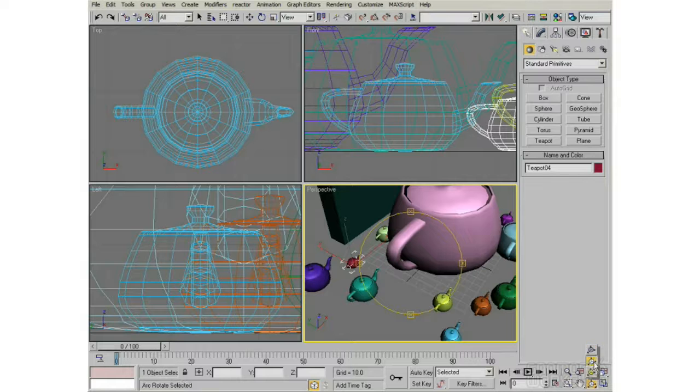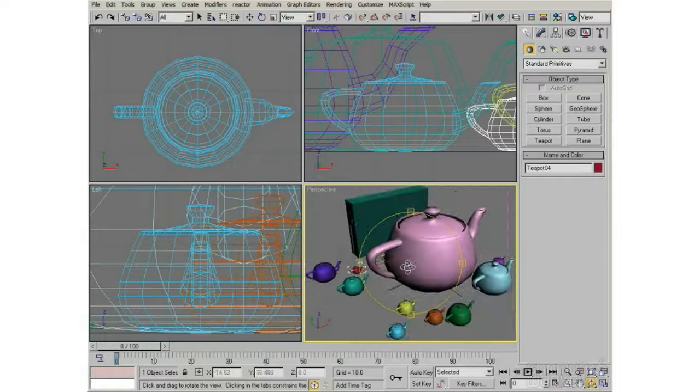And 3D Studio has kind of a subtle convention. When it's gray, it means it applies to the scene. So even like here, you have a gray one and a white one, and in here you have a gray one and a white one. That pertains to scene or camera or whatever, and that white pertains to a whole object that you have selected, and yellow usually means do something to, or rotate around, a sub-object selection. Now, sub-object selection is something that we're going to talk about quite a bit because it is an incredibly powerful way of modifying objects.